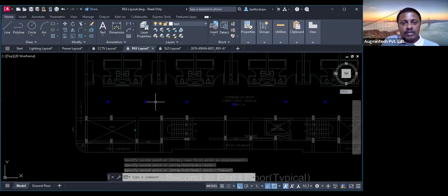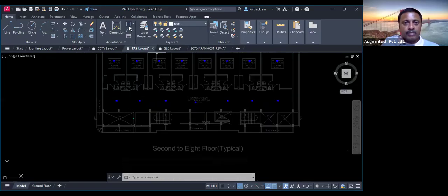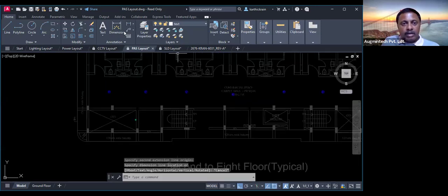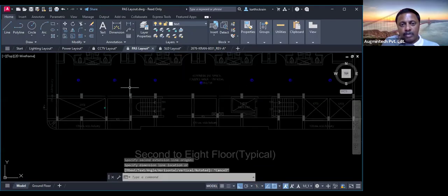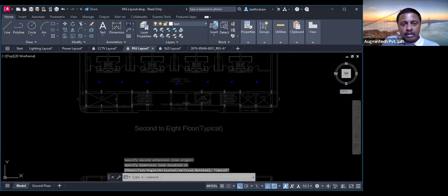As per the requirement. So now you can maintain that space also, like that 5.4 will be available or less than 5.4, right? That's what is required for us. So how much it is? It's like 4.8 meters. Fine. And this one, like you can see, it's like around 5.2 meters. Well under 5.4, and it's not such that equally we have to maintain, because it depends upon the other services also that are there, right? That also we have to consider.